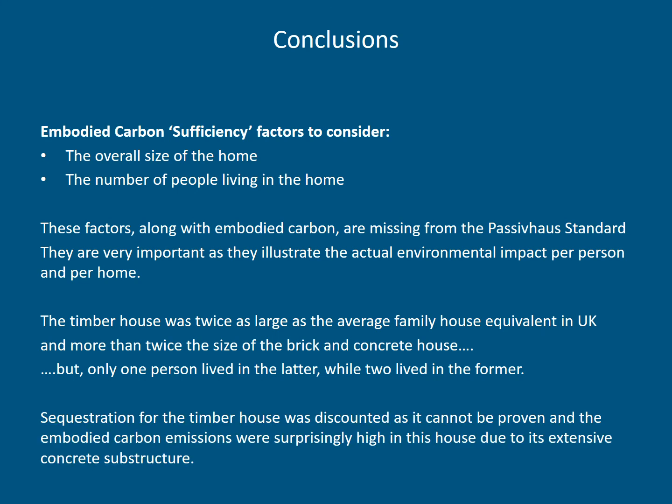We didn't use sequestration for the timber house because we can't prove the supply chain, and we also can't prove whether or not the timber house will actually remain standing long enough to account for all the sequestration over a long number of years. Once this was removed, the embodied carbon emissions were surprisingly high for the timber house, and this was also due to its extensive concrete substructure.